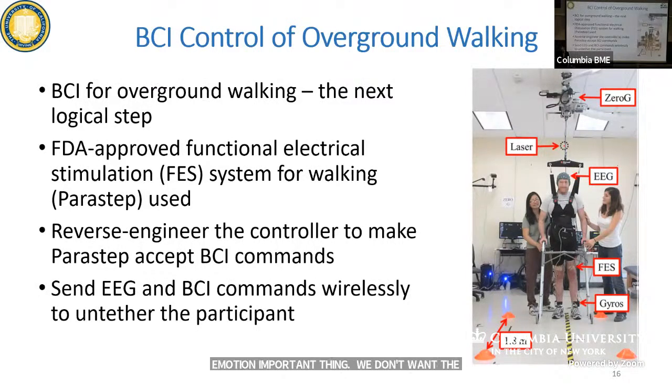And a lot of, as I said, homemade products, including our gyroscopes here. You see here the muscle stimulator. These are just big electrode pads on the quadriceps and tibialis anterior, which is responsible for foot dorsiflexion. This is very strong voltage, by the way, probably up to a couple hundred volts. So this specific individual doesn't have sensation. This would be very painful for somebody who can sense the signals, so certainly not recommended for those who have unimpaired sensation.